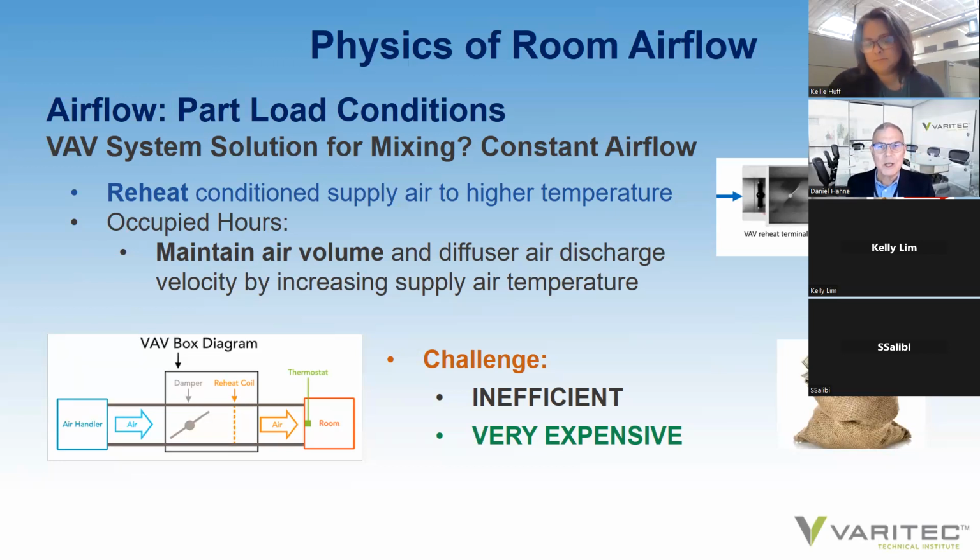In my Psychrometrics Deconstructed 2 presentation, I illustrated that psychrometrically, on what conditions. It could be, with the case that I showed, that you would need a 48-degree dew point off the coil to at least approximate a room condition of 75 degrees, 50% RH. So maybe you need a dew point of 45 degrees off the cooling coil to absorb the moisture content in the mixed air stream, dumped back into the supply air jet before leaving the air handler.